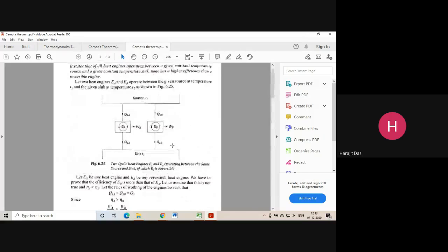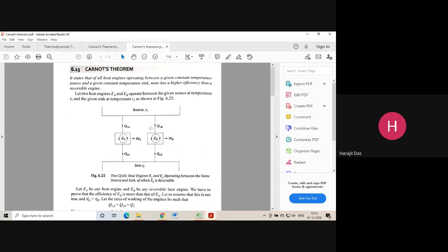Okay, so here one thing I want to tell you, this is the reversible engine. We have taken this example before also. When the reversible engine was producing some efficiency, the definition of the efficiency is WB upon Q1B, isn't it? Output upon input, this is the input, this is the output. This will be maximum when Q2B will be minimum, isn't it? Because WB directly depends upon this minus this. So if this is minimum, then only WB will be maximum. So efficiency will directly depend on this ratio WB upon Q1B. So for a reversible heat engine, always this will be minimum.